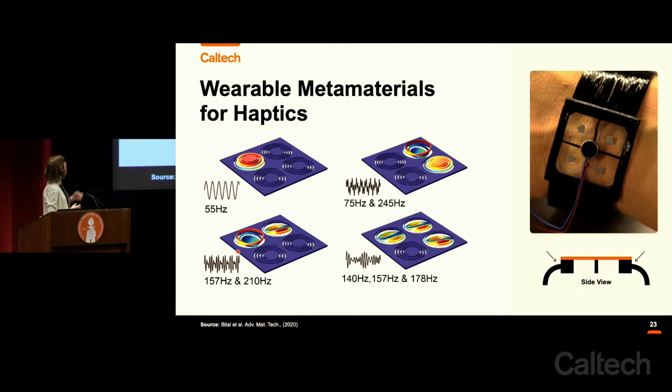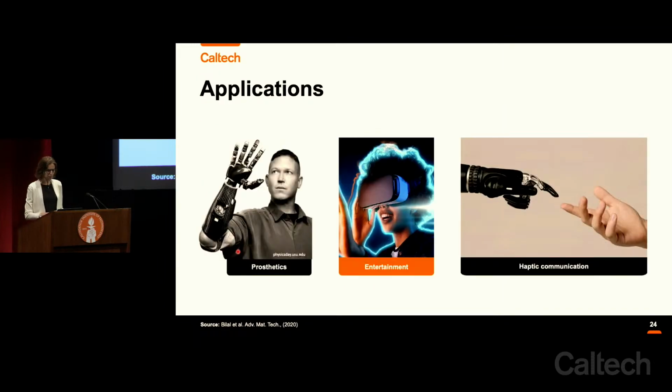So what I mean, and you see snapshots in this video, is that some of those coils can vibrate up and down, others can tilt left and right, and others can shear horizontally. And each one of these motions encodes a different sensation upon contact with the skin. We studied this mechanically, but we also corroborated the work by user studies conducted on volunteers to open new avenues for wearable and robotic interfaces and communications.